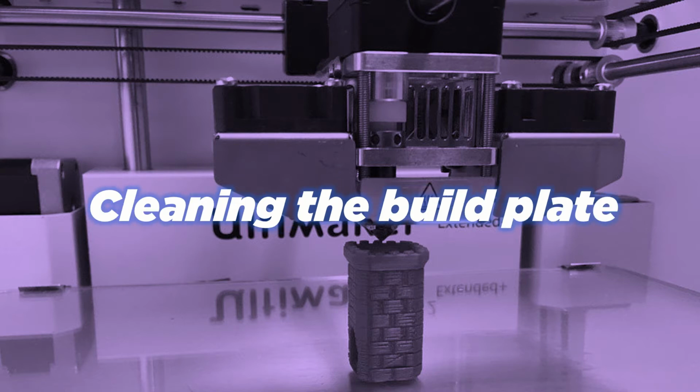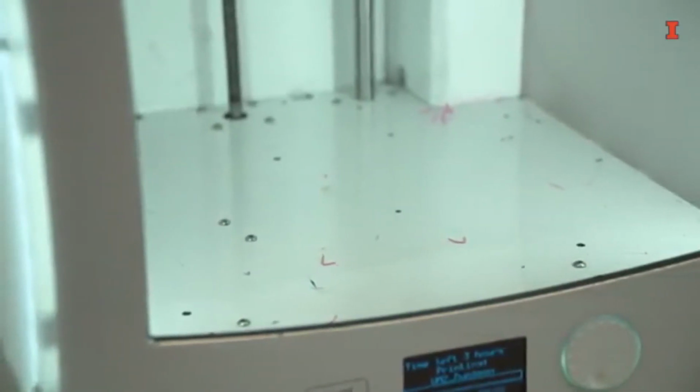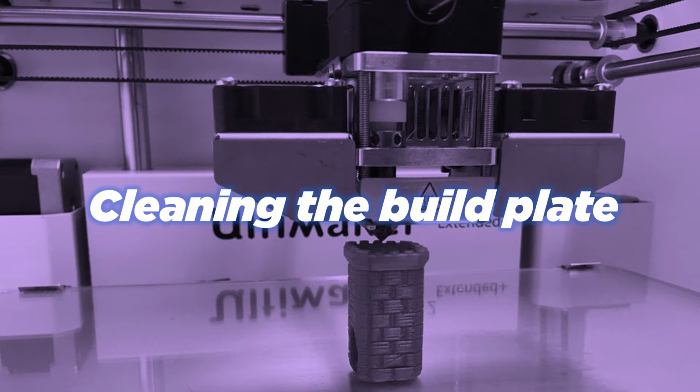Okay, now cleaning the build plate. Here's another moment where the mechanical system meets the extrusion system. If you do not confirm that you have removed the last printed part from the build plate along with any detritus, there are chances the tool head will blissfully plow into the printed object. Your 3D printer needs you to take a second and clean and prepare the plate for a new print.